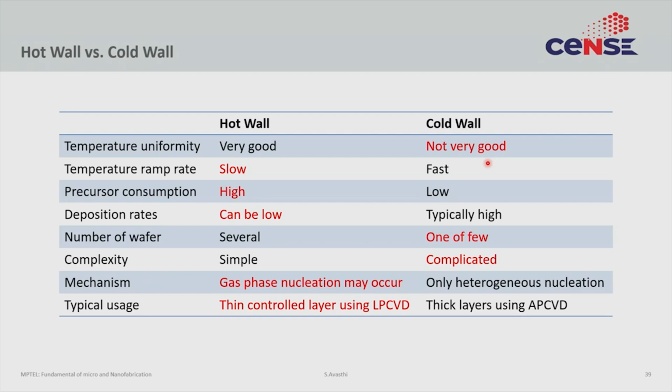The mechanism of nucleation, we will discuss this later, but hot wall reactors can have gas phase nucleation. Cold wall reactors only have heterogeneous nucleation. When we discuss nucleation, we shall see that heterogeneous nucleation is preferable, especially if you are trying to deposit a thin film.